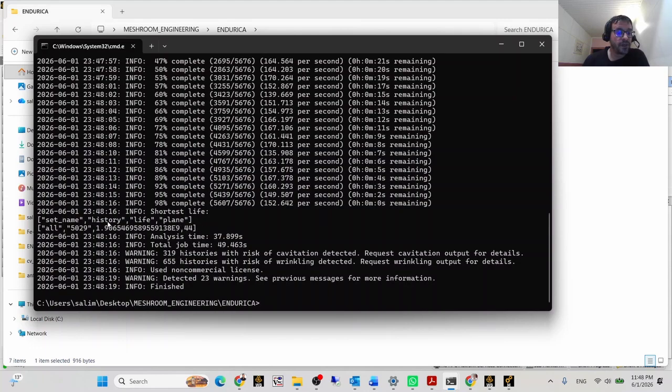So we already have this analysis finished. Once the calculations are done, we have some information here about life and about the critical plane. The critical element is 5029. Life of the most critical element is something like 1.9 billion cycles, and the critical plane is 4.4.